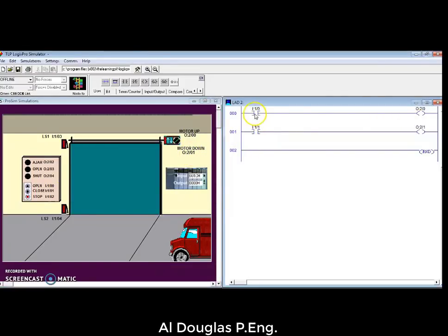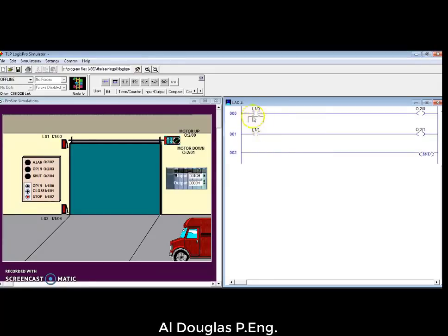Okay, so we have our logic structure drawn here, and our addresses we just drag over. Whenever we draw these things, we're always going to want to document what we're doing so we can tell what's what. I can't tell what these things are just by looking at them. So I'm going to right click, go to edit symbol, and put a name on this. This one was the open PB.